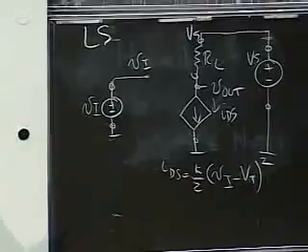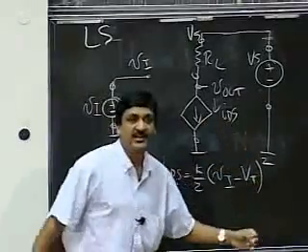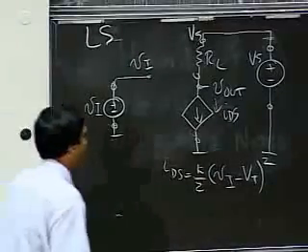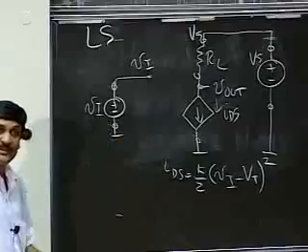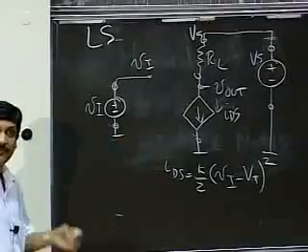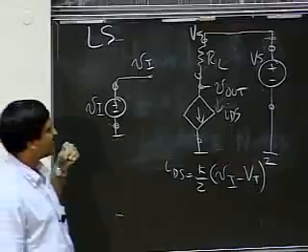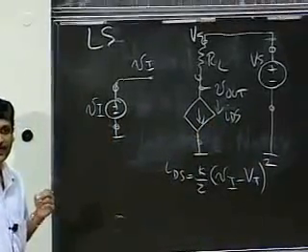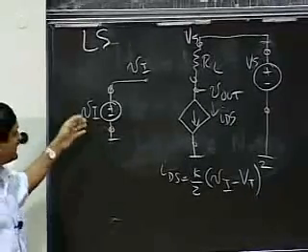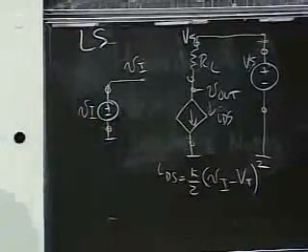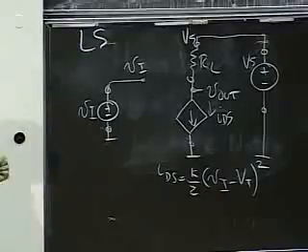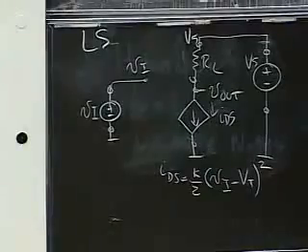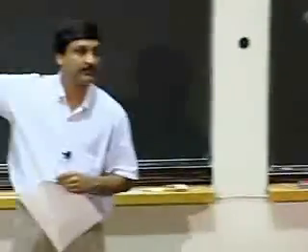And then once I have a linear circuit, I should be able to analyze that linear circuit using methods 1, 2, and 3, superposition, Thevenin, node method, and so on. And certainly the intuitive methods like superposition and Thevenin make life a lot easier for me with linear models, and thereby get the function that I'm looking for very quickly. So again, my claim is that I can replace each of these large signal models by just small signal equivalents, and then just analyze the resultant circuit. And I claim that I should be able to get the same answer.